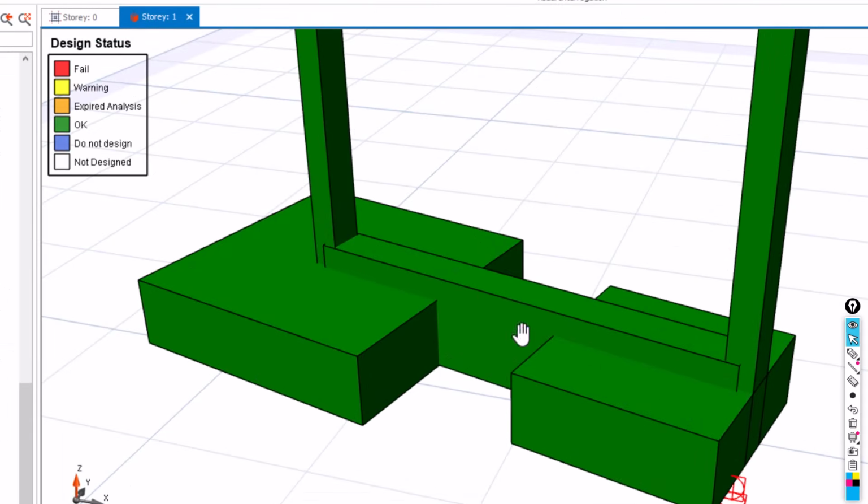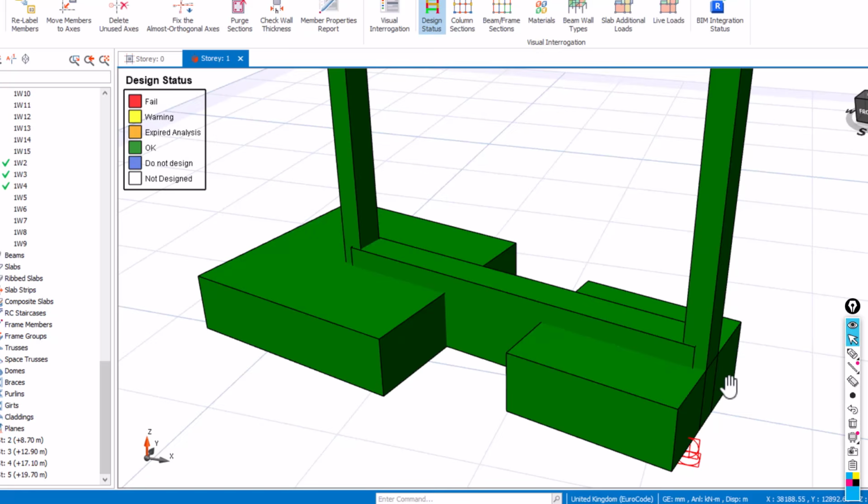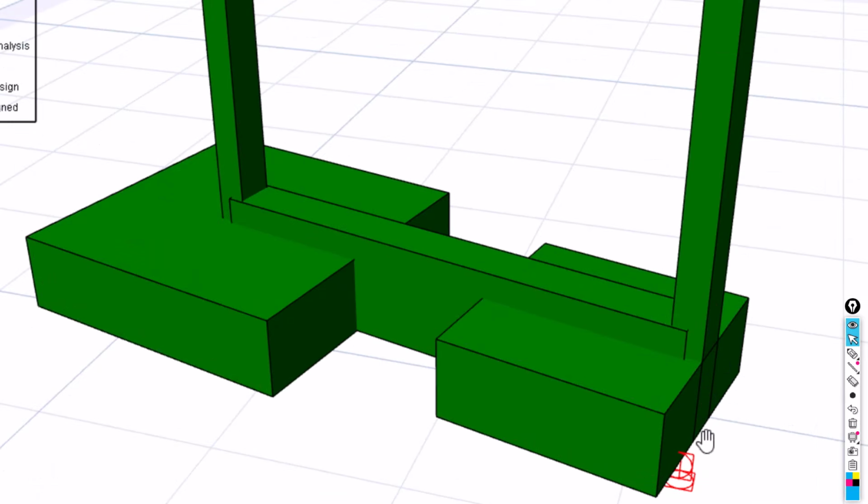This looks like a strap beam connected to an eccentric footing, but basically it is no longer functioning as a strap beam from the principle of how a strap beam should function. Right now it is functioning as a foundation beam, but a strap beam is not a foundation beam; it is just a transfer member to transfer the load and also to counter the overturning moment, which is happening around the eccentric footing.